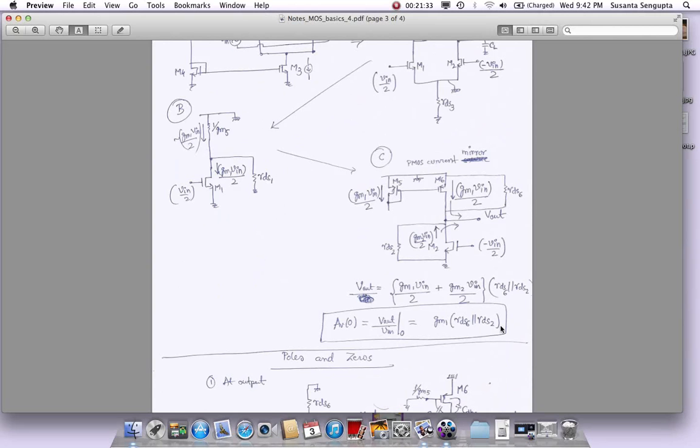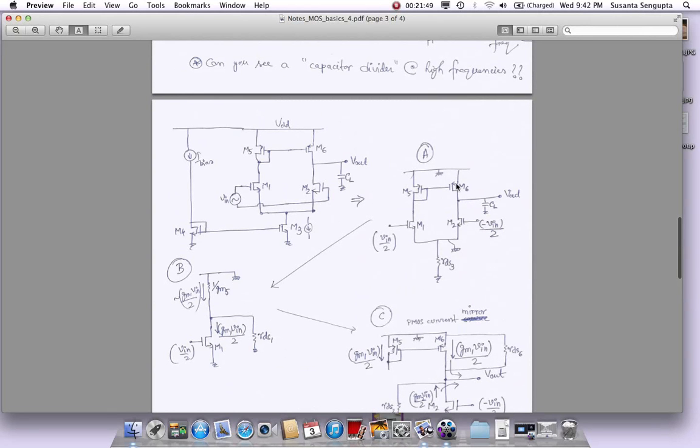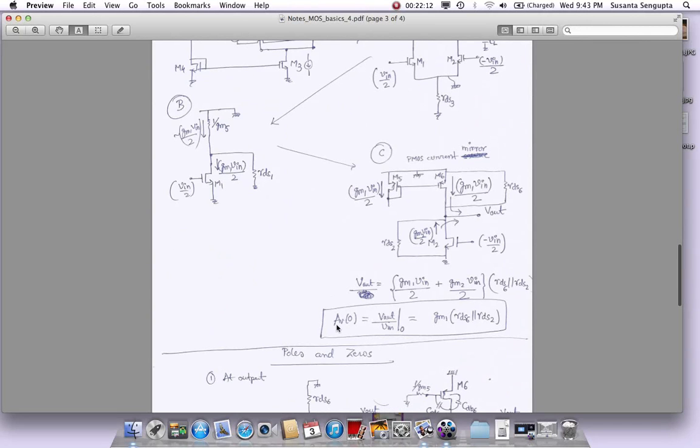So these amplifiers, which are used in one of the classical two-stage op-amp topologies, this is the first gain stage of it, and could provide huge gain. That is the DC gain that we have determined without actually making the small-signal model of 4 transistors, because believe me, if you had 4 of them, it would get pretty complicated to manage. But this way, intuitively, just tracing the currents, what voltage causes what current, where the currents go, and finally what current goes out to the output and what is the total resistance there, that gives you the Vout. So that's one way you can find the gain.